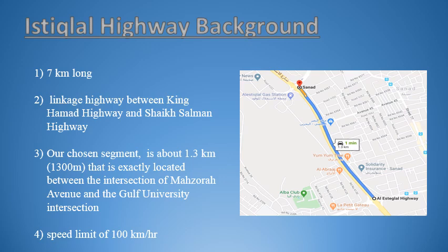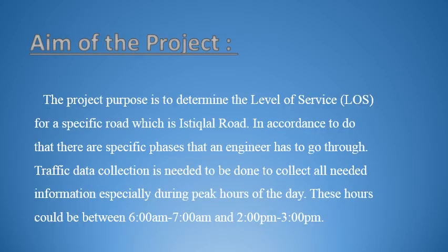Since it is a highway that takes you to different locations and links between highways, it can be very busy and cause traffic jams at peak hour. The purpose of our project is to determine the level of service, which we will see at the end of our slides, for a specific road, which is Istiqlal Road. In order to do that, traffic data collection needs to be done to collect all needed information, especially during peak hours of the day. These hours could be between 6 a.m. to 7 a.m. and 2 p.m. till 3 p.m.